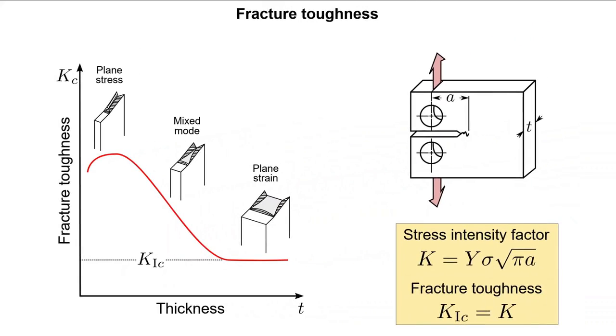This is the basis for the material property of fracture toughness. It quantifies a material's resistance to crack propagation. It is assessed by specimens that have adequate thickness to ensure that a minimal value is obtained, so that it is universally applicable to all loading scenarios while remaining conservative.